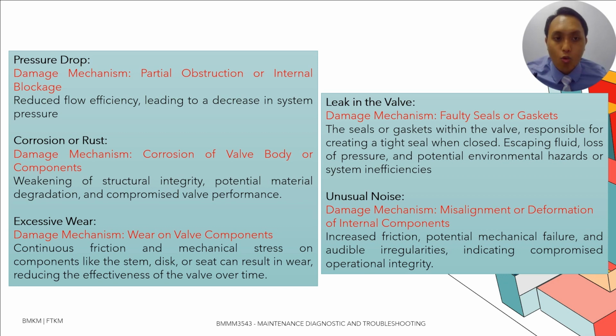Damage mechanism: wear on valve components. Continuous friction and mechanical stress on components like the stem, disc, or seat can result in wear, reducing the effectiveness of the valve over time. So that is the damage mechanism from the symptoms that we recorded.